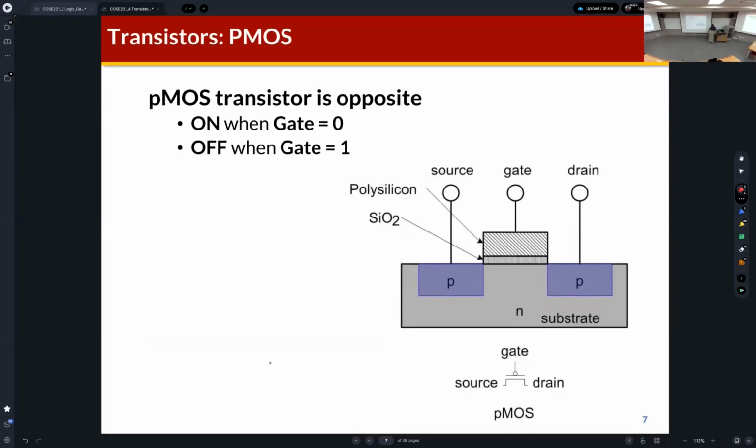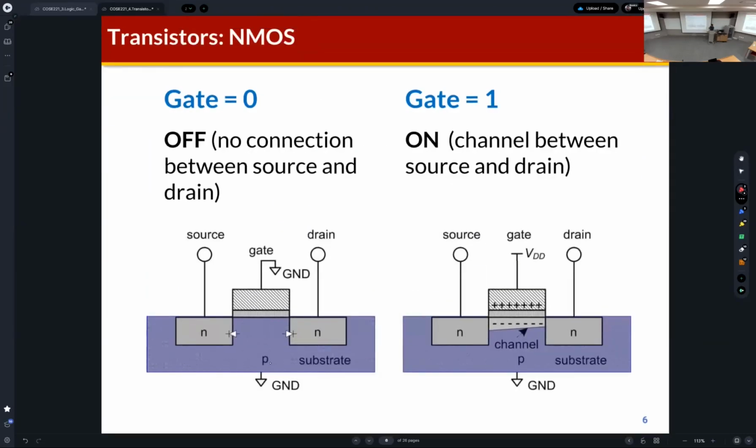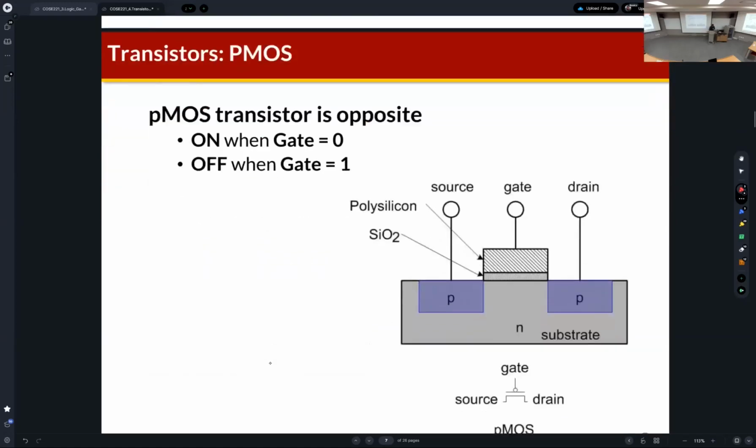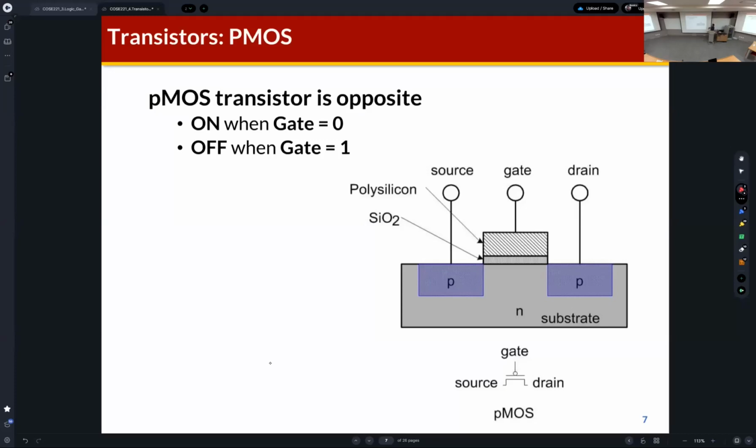And then actually there are different types of transistor called the CMOS transistor. I explained about the NMOS transistor here, so you can see the title of the slide. But the PMOS has the opposite characteristics. So the P well is here, and then you can find the N type substrate. And then this is the symbol of the PMOS transistor. So what is different?